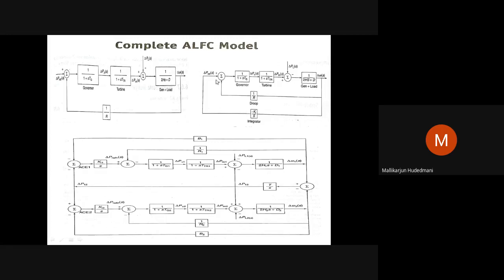was discussed here. Before this, there is an integral controller taking care of deviation of the frequency of that area. So now we can see this is the point where I am speaking of delta P reference 1. Behind this I have an integral controller, KI1/S, this kind of representation. Similarly, behind this in area 2, before the reference set point, who is going to set it? It is the integral controller. To this, some input has to come. We will see what is that.